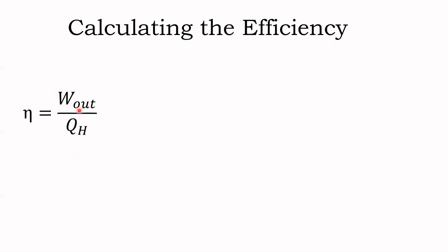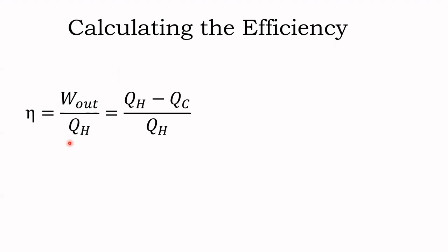Okay, so we'd like to get as much possible useful output work compared to what we bought in the form of gasoline. Well, the first law of thermodynamics tells us that the output work is whatever's left over after you subtract the exhaust heat from the heat absorbed from the hot reservoir. So again, this notion of exhaust is different from exhaust stroke.